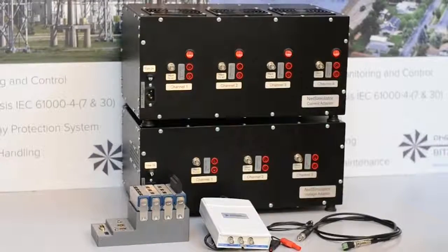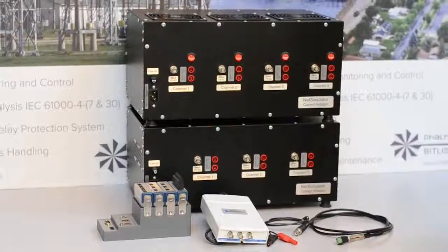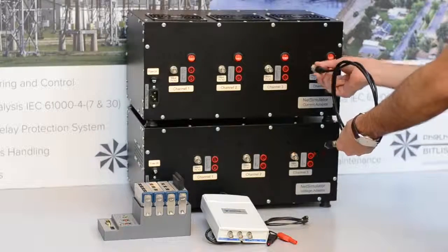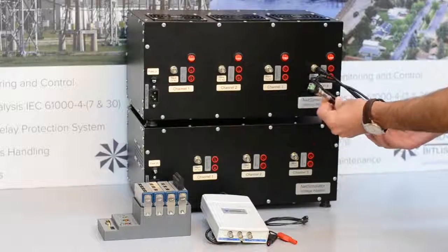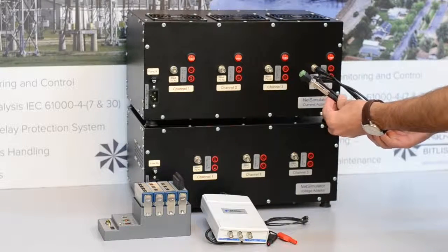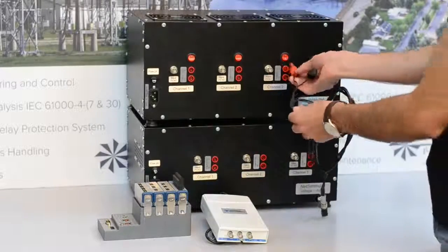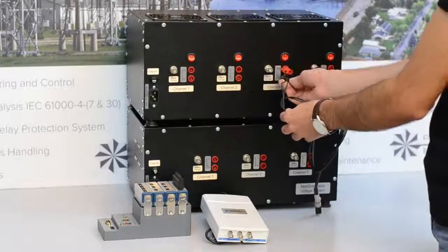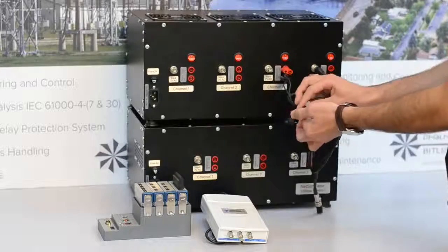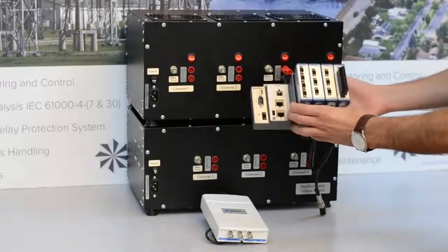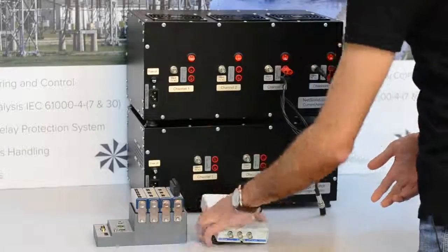Now, when we have a general idea about the system, let's go to the demonstration part. Firstly, we need to power up the adapters and connect the input and output cables. The black BNC cables are used for input signals. The other end of this cable should be connected to the analog output module of PXI. The banana cables are used for output signals. The other end should be connected to our PQA, which we will use as a measuring device. In addition, we will use another measuring device, an oscilloscope.